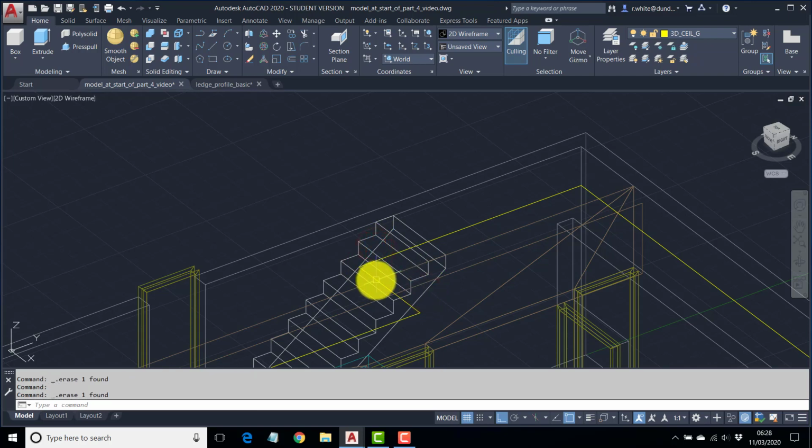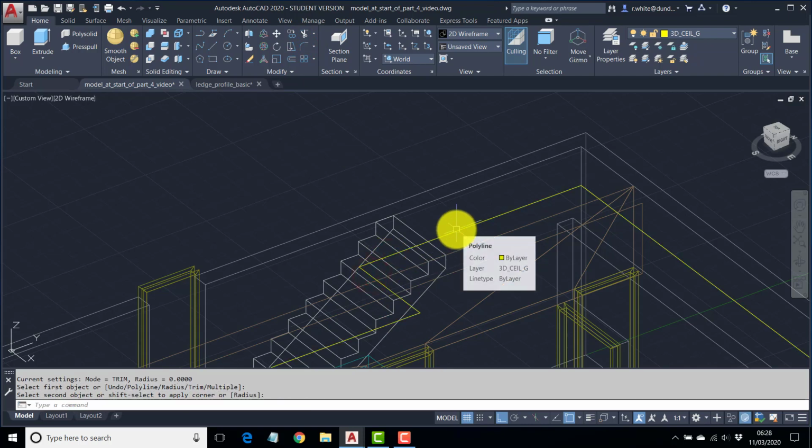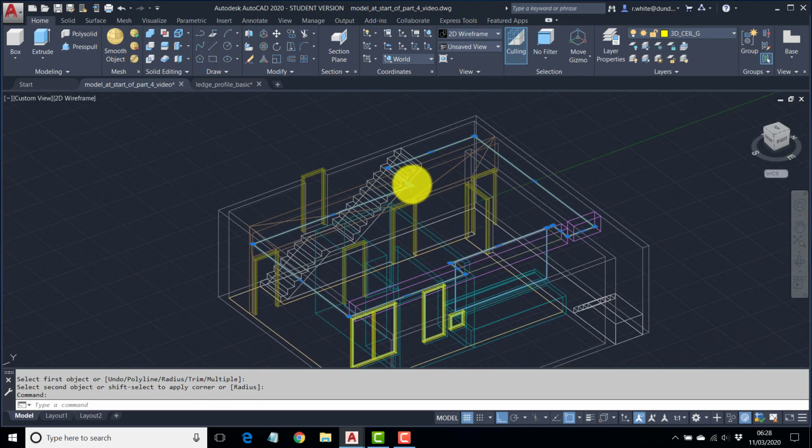Delete those two lines. These are separate polylines at the moment, so you can fillet those two together. That works usually quite happily. If I can find fillet, there we are. Pick one, pick the other. This should be a single polyline now, and that can become a region.